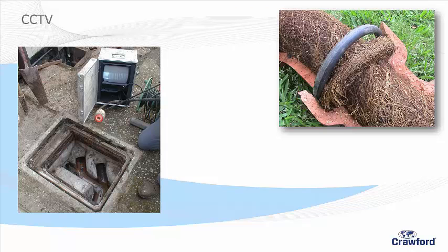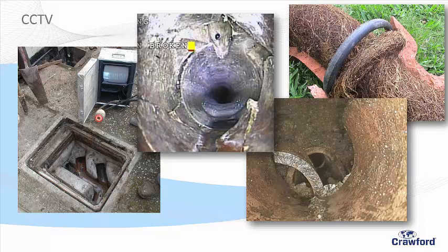You might get totally collapsed drains as you put the camera through, and that's fine. You might even find some friends in the drain, and that's fine too. But these are not caused by subsidence, it's a secondary effect, and we have to eliminate that. Because third parties or neighbours will argue that's the cause of damage, and you say, no, that's the defects we found. I've got dry clay. I haven't got wet clay, which is possibly what you're arguing.